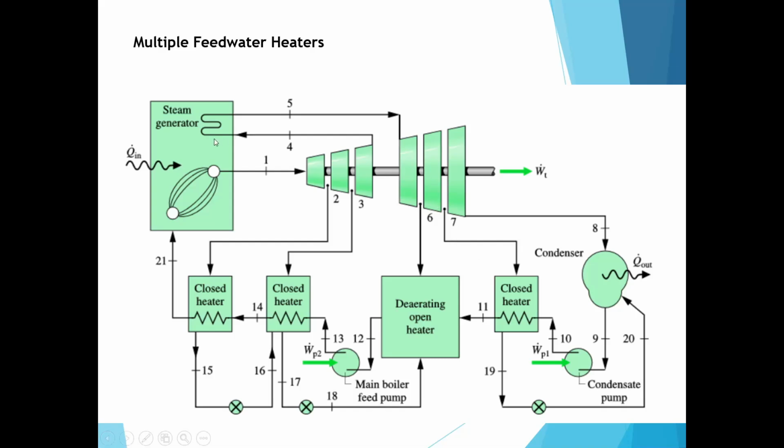If you look at the main path, this one has a two-stage turbine. You have a high pressure turbine, then you have the reheat, then the low pressure turbine section, so basically you have two sections, high pressure and low pressure. Then at the intermediate point, some of the steam is drawn back for feed water heating, right? So in this diagram, you have the main path going here, then to the high pressure turbine, then reheated again, then the low pressure turbine, and back to the condenser, right?